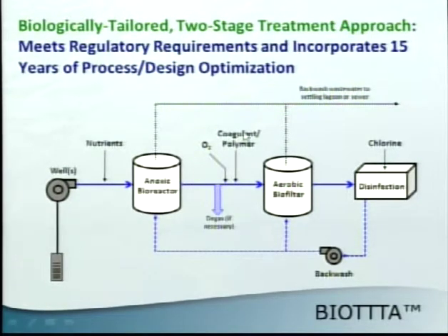Coming out of that system, you've got to add your oxygen back in. You can do that a number of ways. Aeration has been talked about the most. We use hydrogen peroxide. That does a number of things for us. It re-aerates the water, also gives us some oxidizing capacity, and it's also extremely efficient at degrading the EPS, or the slime that bacteria tend to produce when they reduce contaminants.